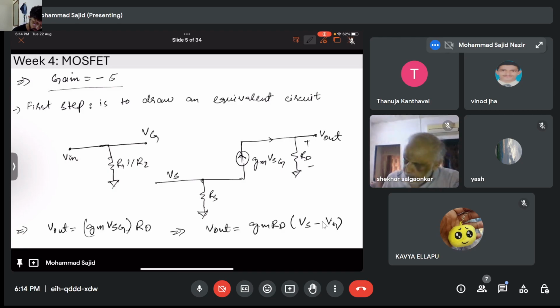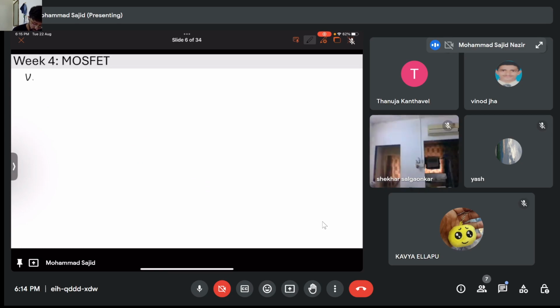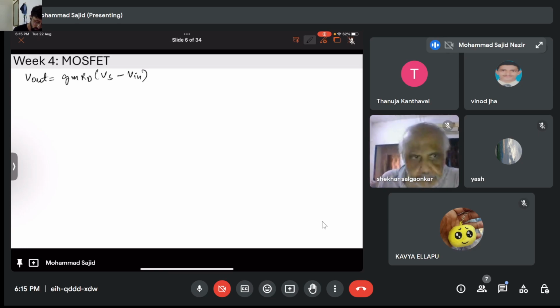And here, if you see, this is at a potential of Vin, that means Vg is at a potential of Vin, right? So my V out is simply equivalent to GMRD times (Vs minus Vin). Now we have another unknown here, that is Vs, right? So we need to calculate Vs as well.